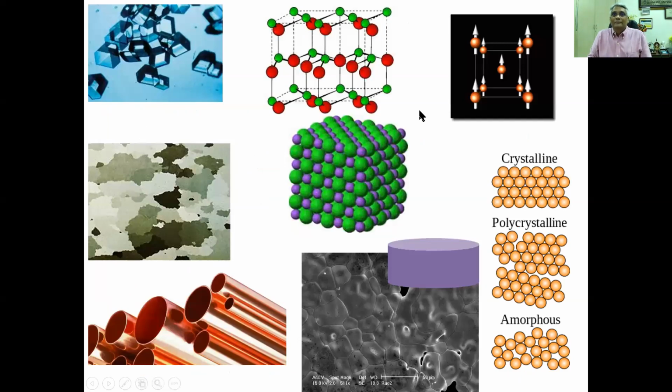So this is a basic building block, the unit cell, and another example of a slightly more complex unit cell. This is what is meant by perfect periodicity, where you see atoms arranged in a perfect periodic way. That's what is meant by long range order. You see the way this set of atoms is arranged, and you'll see the same thing on the extreme other side also, without any crystallographic misorientations or breaks, or dislocations and other crystallographic defects.